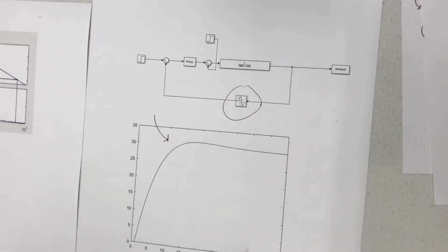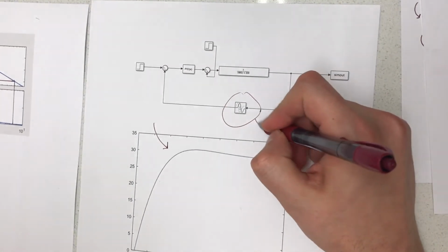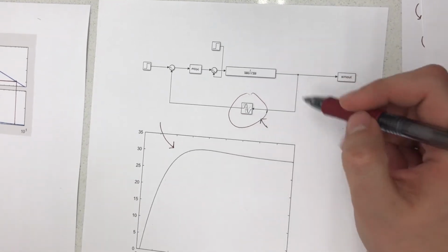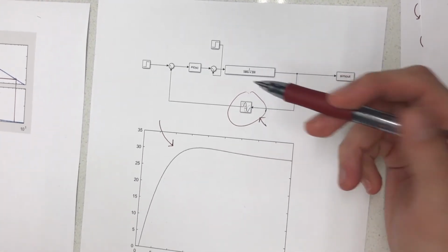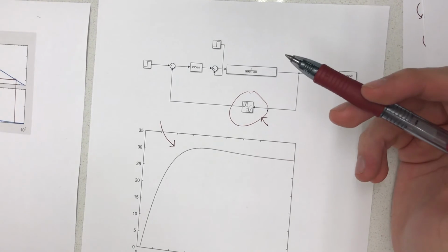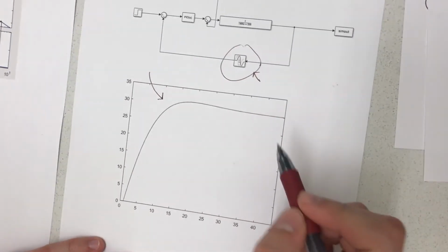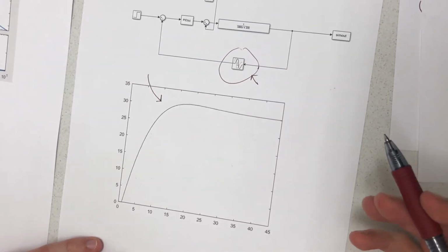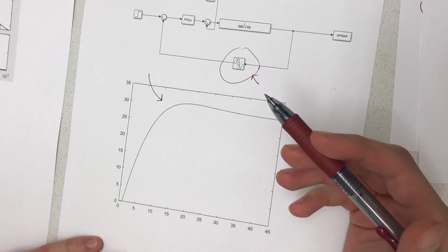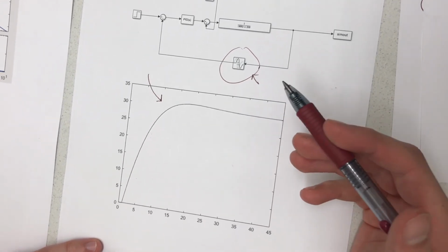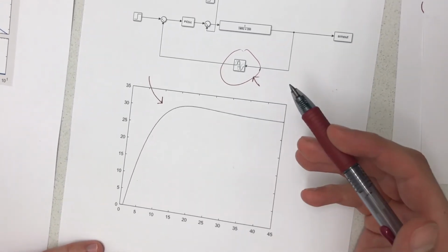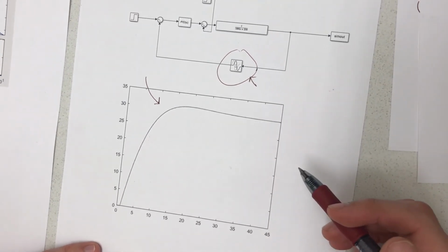Finally, we plugged that into Simulink with this time delay operator, and in here we plugged in 0.25 seconds to see how our system would react. And as you can see in this graph, our system did not go out of control. We did have a slight rise in our percent overshoot as well as our rise time, but overall our system is still stable.